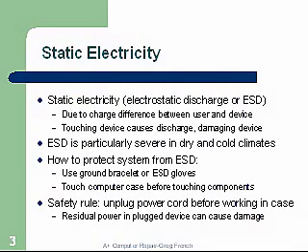Static electricity, electrostatic discharge, or ESD. This is due to a difference in charge between the user and the device. Touching a device causes the discharge or the damage to the device. You don't have to do much. You can just rub your arm across your shirt or your blouse and touch a component. That's usually enough static electricity to damage a component. ESD is particularly severe in dry and cold climates. So if it's dry, you can go across the carpet and pick up static electricity and feel a discharge. That's a big threat to a computer.